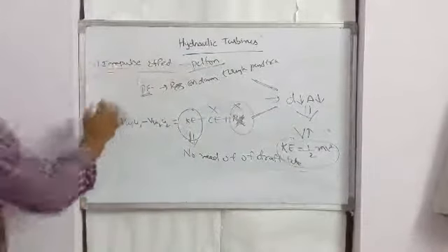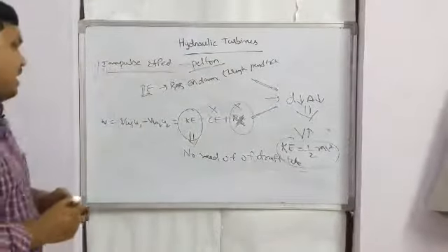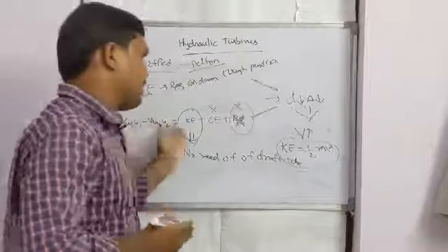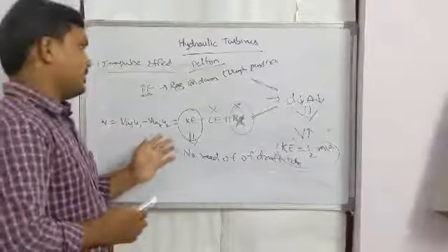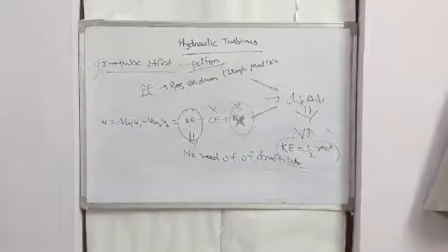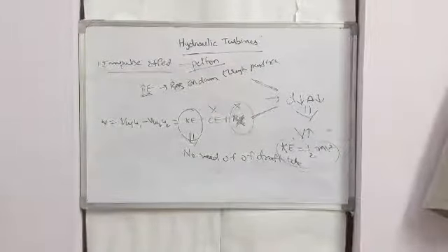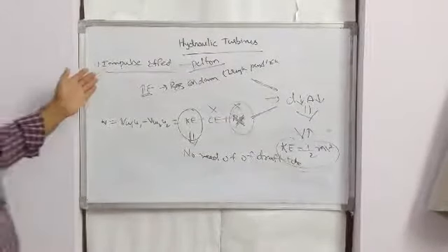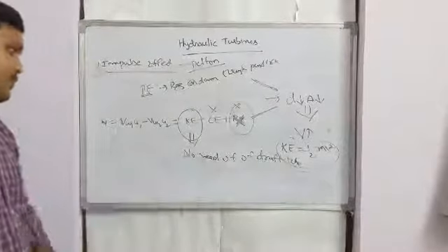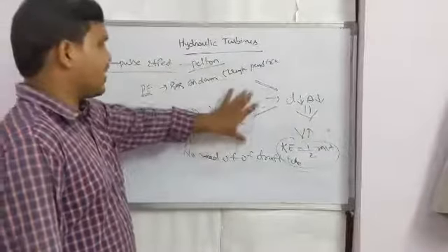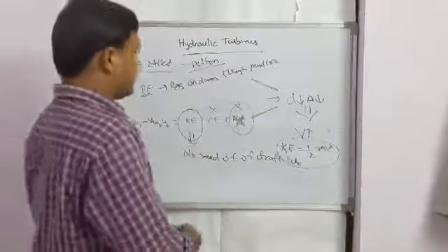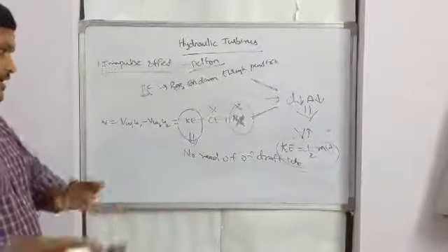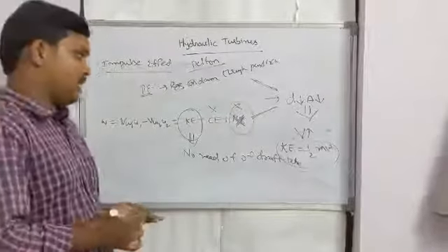In the impulse effect, the available energy is converted completely into kinetic energy. Only kinetic energy plays an important role. The entire turbine works in an environment that is called atmosphere. So in the impulse effect there is no need of a draft tube. The draft tube is needed where we need a reaction effect, for increasing the pressure energy or the kinetic energy, that is, the change of pressure energy and kinetic energy vice versa.